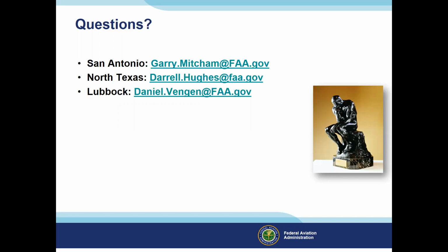And the emphasis is not that that iPad or that GoPro is installed in your airplane. What is important is what it is attached to in that airplane, because the attachment of anything that's permanently installed in the airplane must be installed in accordance with approved or acceptable data. Depends on if it's minor or major.